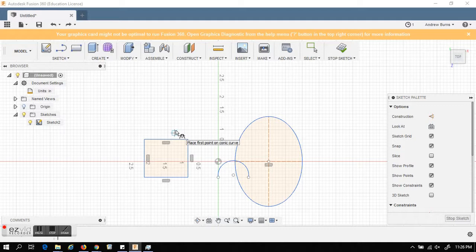What you do is you set 2 points first, and then you set where the vertex is. So kind of weird, but afterwards you can then set the tangency constraint, which can make it really pointy or really flat.